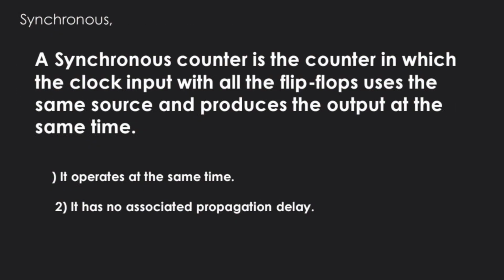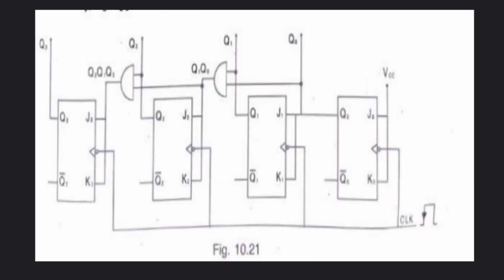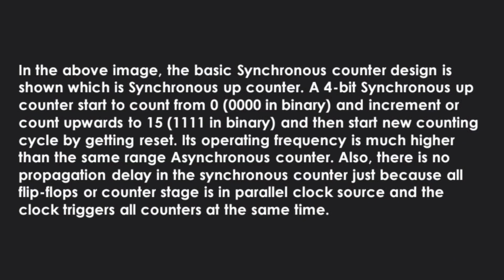Synchronous counter. A synchronous counter is a counter in which the clock input of all the flip-flops uses the same source and produces the output at the same time. It operates at the same time. It has no associated propagation delay. This is the circuit diagram of a synchronous counter. In the above image, the basic synchronous counter design is shown, which is a synchronous up counter.